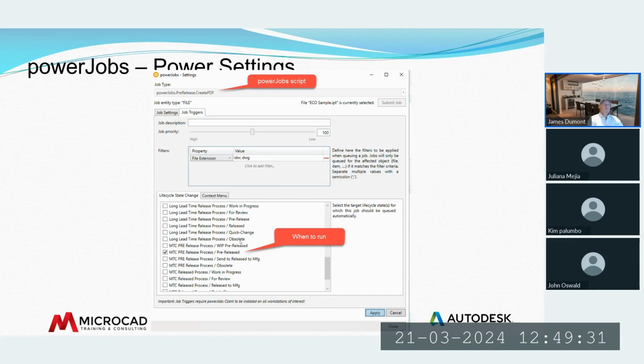The advantage of this is, in normal Autodesk Vault, you do the transition, it'll send both IDW and IPT. IPTs are not supported, but it gets processed and then kicked out because it's unsupported. So you're sending 2 jobs versus 1. Here, you're sending fewer jobs to the queue to be processed, which means everything gets done faster.